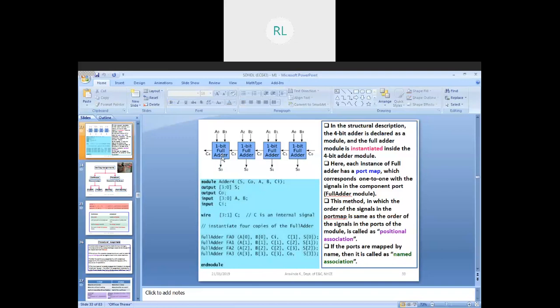Now let us actually build it. Instead of having just one section, we will try to have four smaller modules here, and we will see how the code is going to look. So here you can have a 4-bit adder: a0, b0, giving you s0, s1, s2 up till s3. So a and b get added, and then you have a carry and then sum. So carry sum, carry sum. So that's how this works.